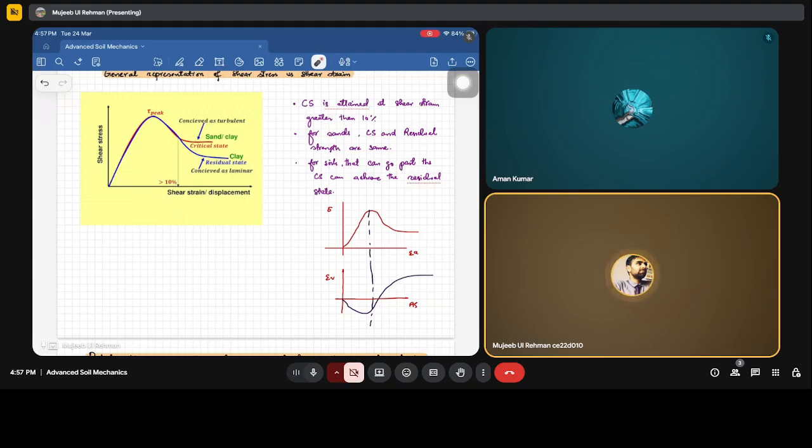So the change occurs only in the accumulation of strains. There will be the accumulation of strains which are responsible for the development of shear bands. There will be shear pockets or small zones of failure, which then combine and become a visible shear band in the specimen.